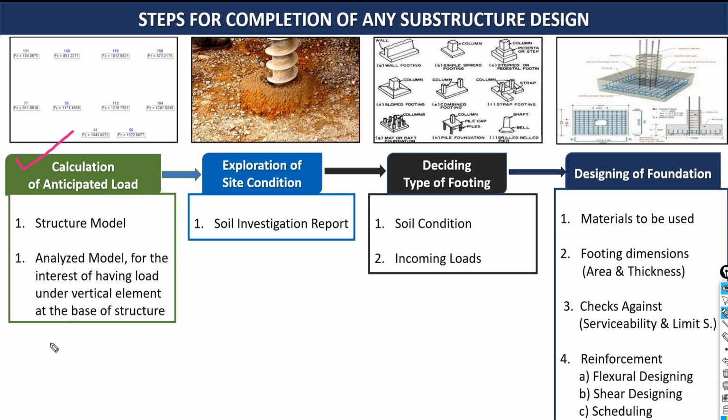Once you get the reaction, once you get the values, then what next? Next is the soil investigation report. Without having knowledge of the soil condition, without knowing the load carrying capacity of your soil, without knowing all other engineering properties of your soil, you can't proceed for design purposes. So first you need to know the loading, how much load is coming. Second, you need to know the soil investigation report for your proposed structure.